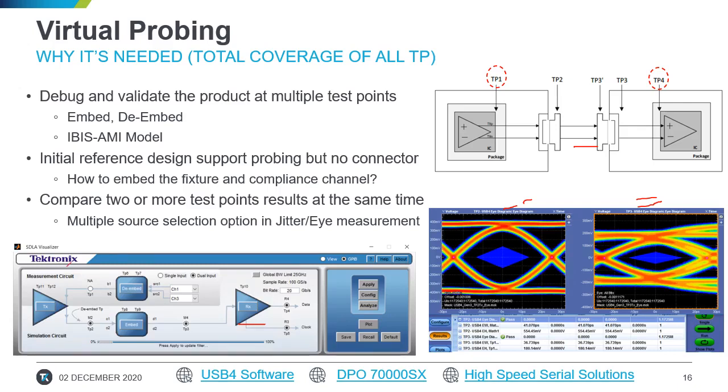Another important thing for virtual probing is when we are using the reference board or reference design, sometimes that doesn't have a connector. It might have probing where we can probe it and see it. But how do we make sure we are close to compliance testing, or how can we do the testing that is close to the real world? We can embed the fixture model and embed the compliance channel to make it TP2 and TP3, and give that effect of connectors and reflections, and make it TP2 or TP3 test points.